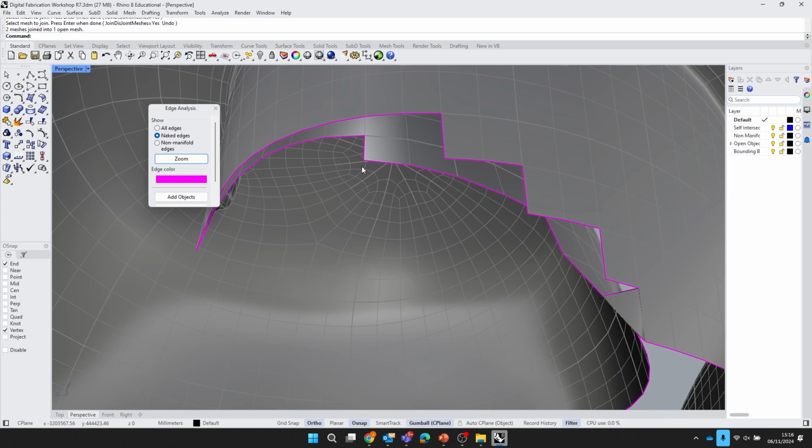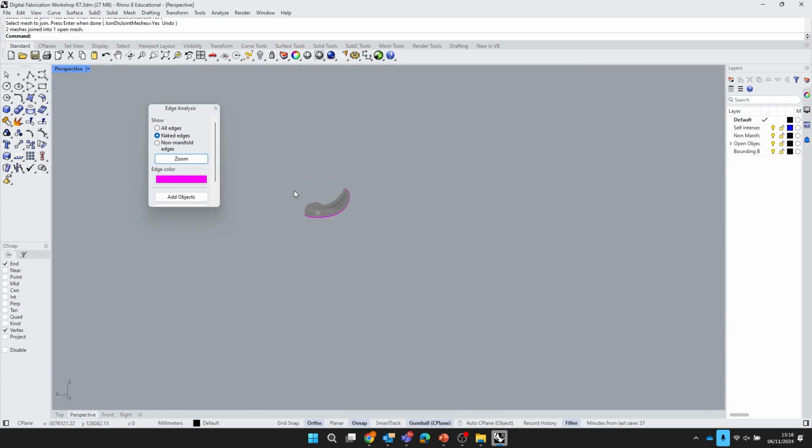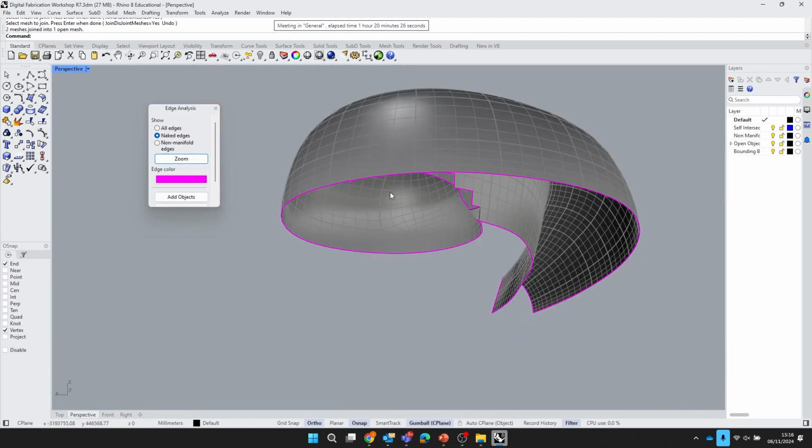It depends. In fact, we'll do one with 10,000 faces in a minute, which is the big site model. What we'll do, we'll add a base to the site model, because that's always good to do. But essentially, yeah, you would. You just do it strategically in a few places, just to break those kind of groupings of holes, and then you would fill those holes separately after. Gives you more control over how they generate.